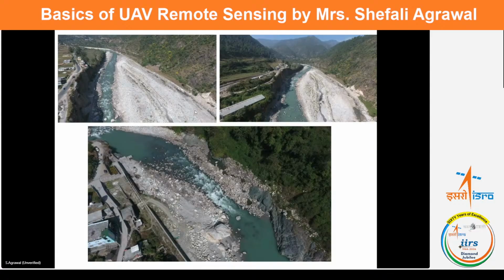Then based on this, ortho rectification is done, and true ortho mosaics, which are free from both relief and tilt distortions, are generated and can be further analyzed. For example, if it's multispectral data, you now have an ortho mosaic created free of distortions. You can create NDVI, do other further analysis on the data, and extract the information as per your requirement.